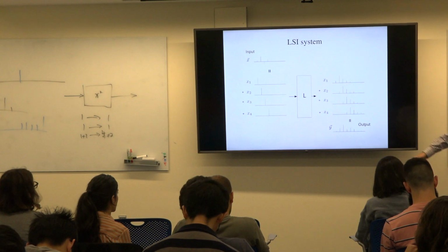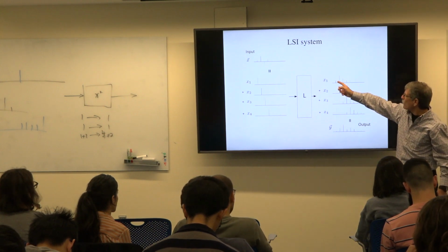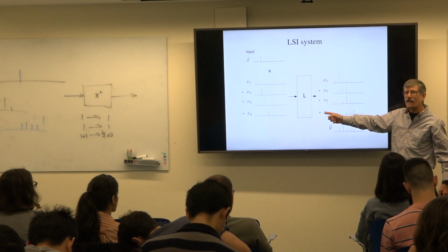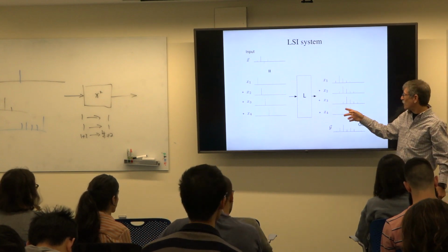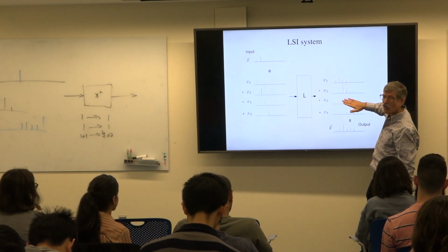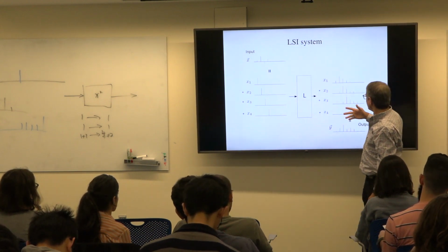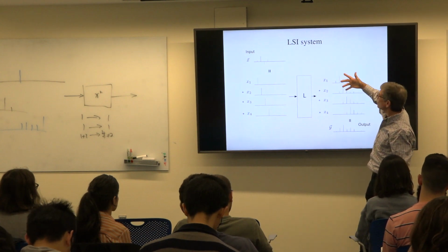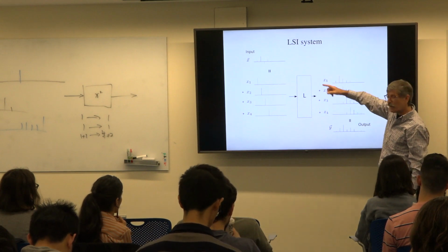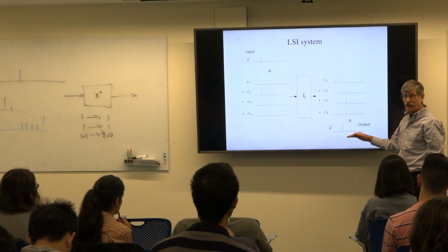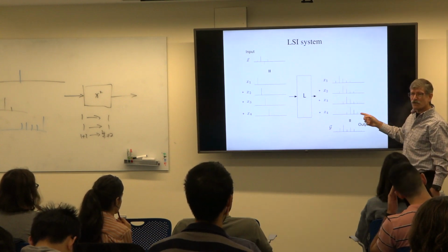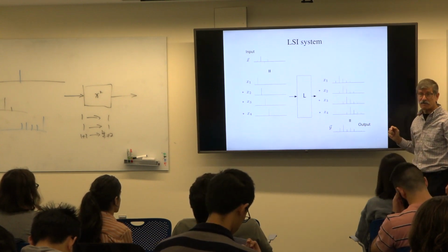And again, it's a linear system, which means that once you scale the impulse response, shifted the right amount, by the amount of the input at that same time, once you make the third one upside down and smaller, and you make the fourth one right side up and a little smaller, and you make the second one a little bit bigger, and the first one smaller, once you do these scale factors from the input, you add them up, you get the output. That's the linearity part. The shift invariance part is the fact that these impulse responses are all the same, shifted. Okay?